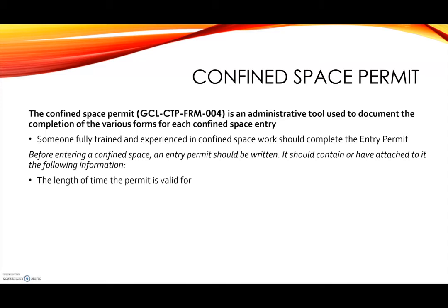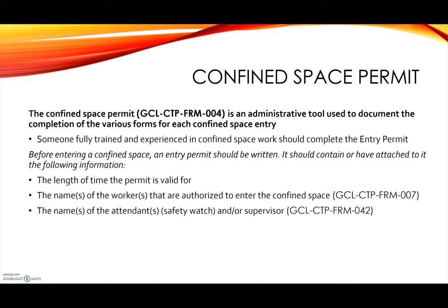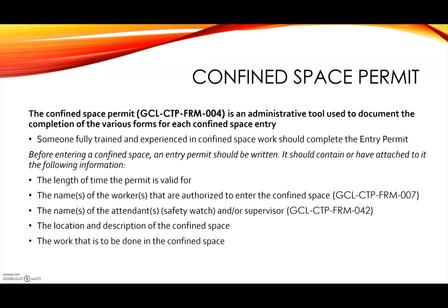the length of time the permit is valid for, the name of the worker or workers that are authorized to enter the confined space, the name of the attendants, attendees, safety watch and/or supervisor, the location and description of the confined space, the work that is to be done in the confined space.